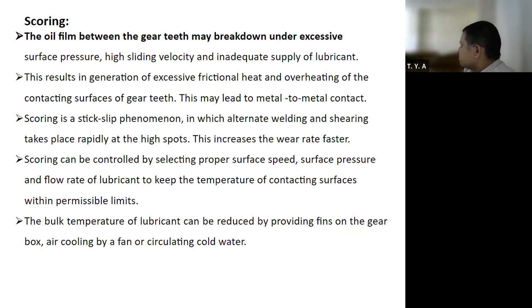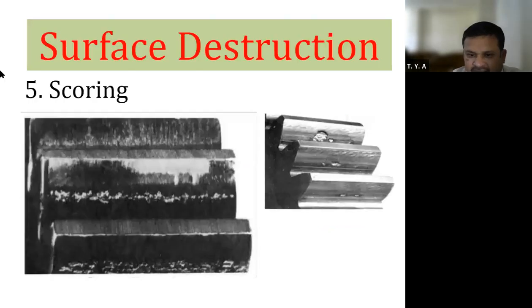So remember, sliding motion causes shearing. What does sliding motion cause? Shearing. Therefore welding takes place, and since in gears two motions exist, rolling and sliding, because of the sliding motion shearing takes place. Shear means like this. The surfaces weld to each other, stick again, come off, and shear. And because of this, what is going to happen? Such types of spots are formed on the surface of the gear. Large pits are formed on the surface of the gear. Large burned pits.